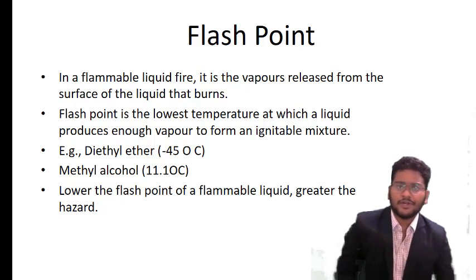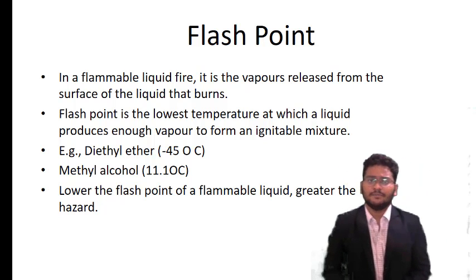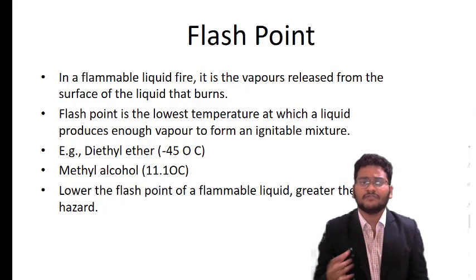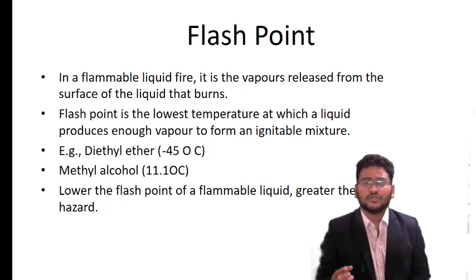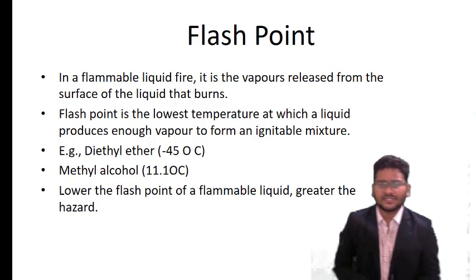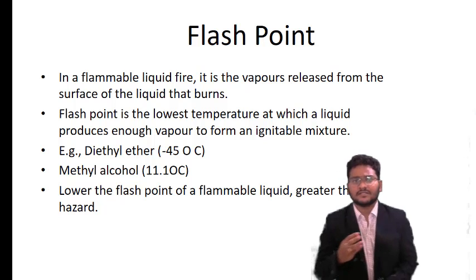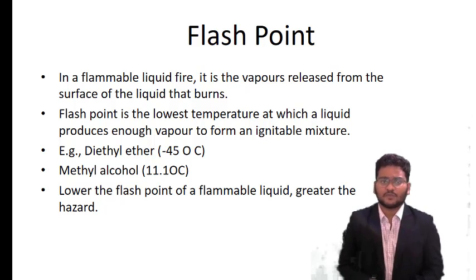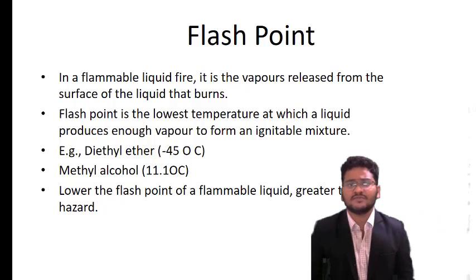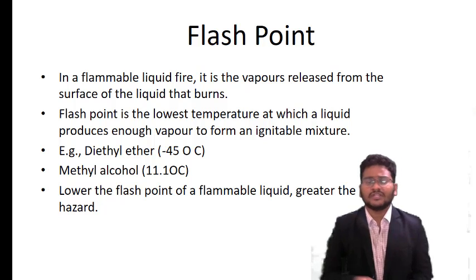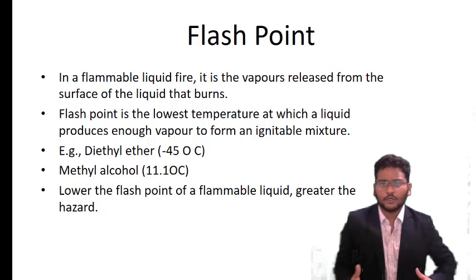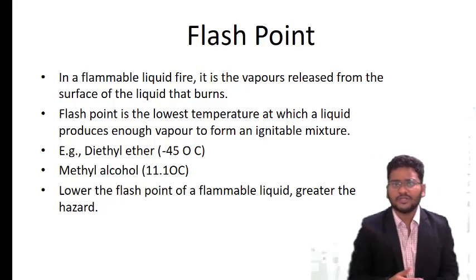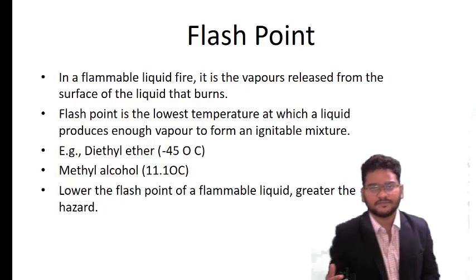Coming to the flash point: the minimum temperature at which the vapors of the substance or the liquid catch fire, the temperature at which the first flame starts. That we call the flash point. Generally, if the flash point is low, it is a very hazardous material, because at a low temperature it will catch fire and harm the substances nearby. So whenever the flash point is lower, it leads to a hazardous substance.